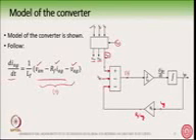So this is the point where I get the difference, and then I multiply by 1 by LF, and then I get this expression di by dt. So here comes the diAG by dt. Then I integrate it. When I integrate this diAG by dt, then I get the IAG back here, and this IAG I will feed back here and complete the loop.